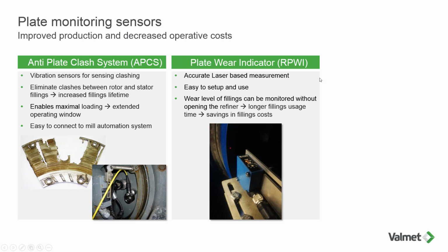Over here we have the plate wear indicator, and what this is, it's a laser-based measuring device that's measuring the total movement and the total distance that the sliding head has moved inside. So we'll start out your refiners with new plates. We'll bring all 4 plate positions together as you would set your proximity switches. And then we're going to measure that. That'll be our 0 point.